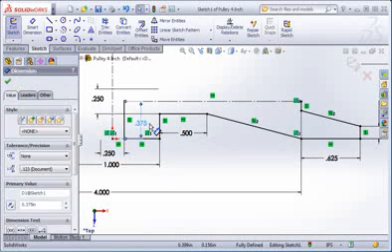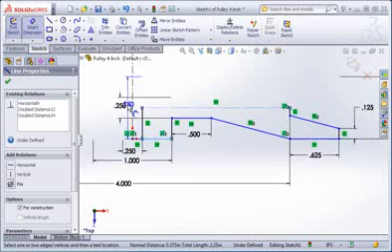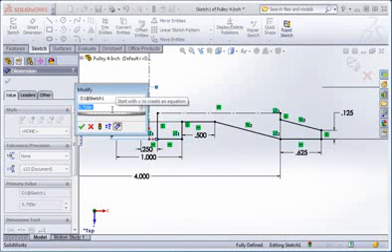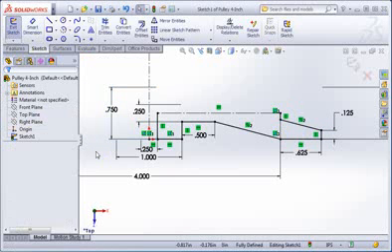Highlight it, and then type the delete key. Now type the D key, and then select the line in the construction line. Place the text above the construction line, and now you can easily see that the thickness of the pulley will be 3/4 of an inch.